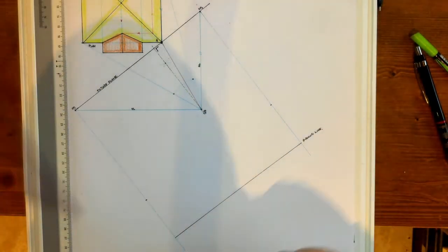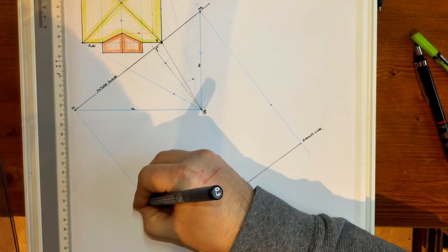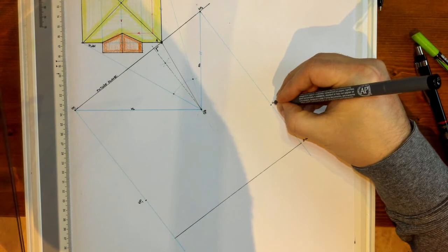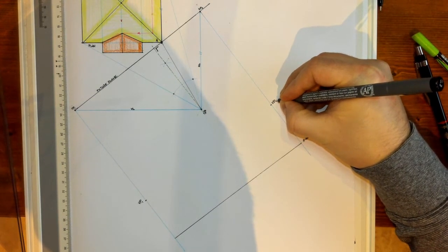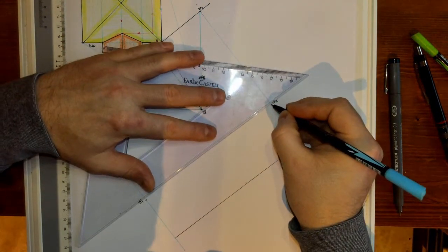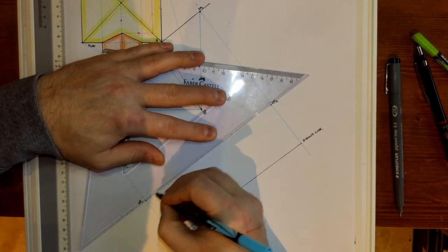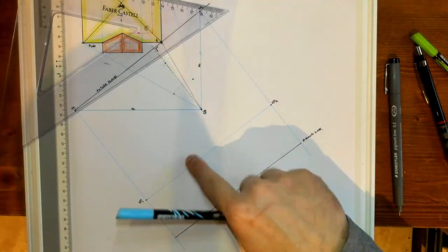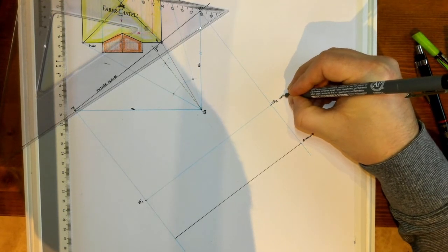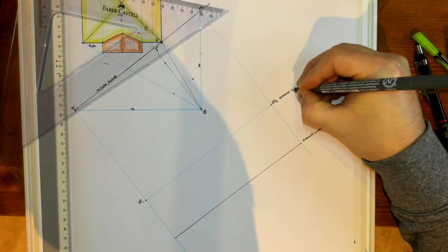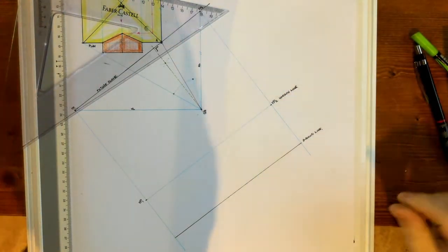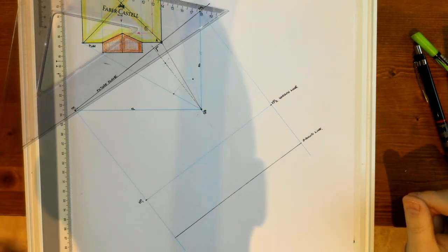Okay, so what we have now in the elevation, because this is our elevation, is VP1 in its position in elevation, and VP2. Okay, and we're going to join them with a very light line. We'll join them with a very light blue line there, like so. That's the horizon line. Both vanishing points are contained on the horizon line. Well, in effect, the vanishing points create the horizon line too. So they're both equally important.